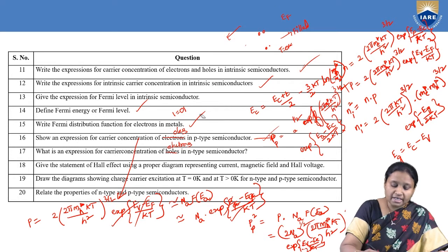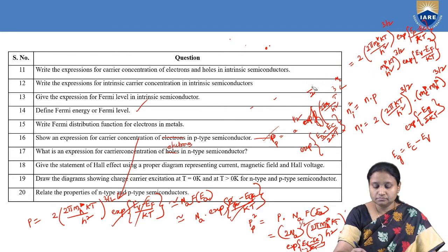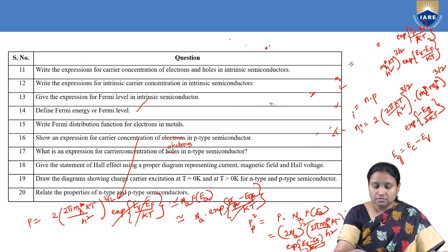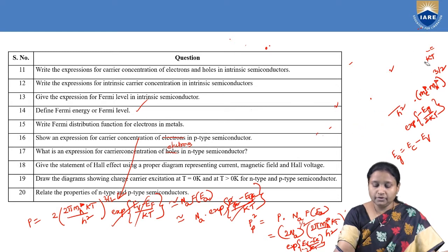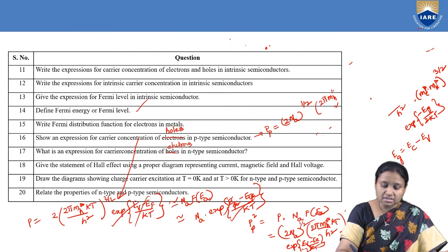So if we write this expression clearly, coming to the density of holes in p-type semiconductor, it is given as p_p = (2Na)^(1/2) into (2πmh*kT/h²)^(3/4) exponential (EV − EA)/2kT.